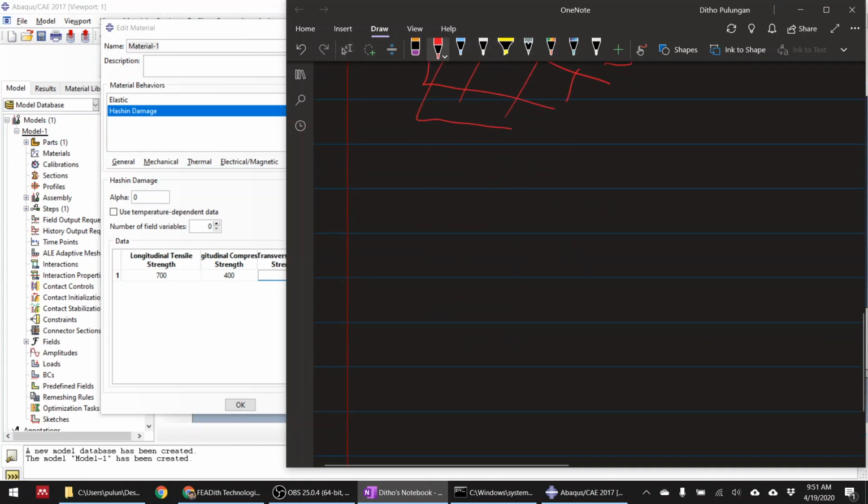What happens is you will see the laminate with small fibers like this, distributed randomly inside the matrix. So when you try to pull in this direction, there will be a crack in the matrix, or sometimes what we call fiber matrix debonding.